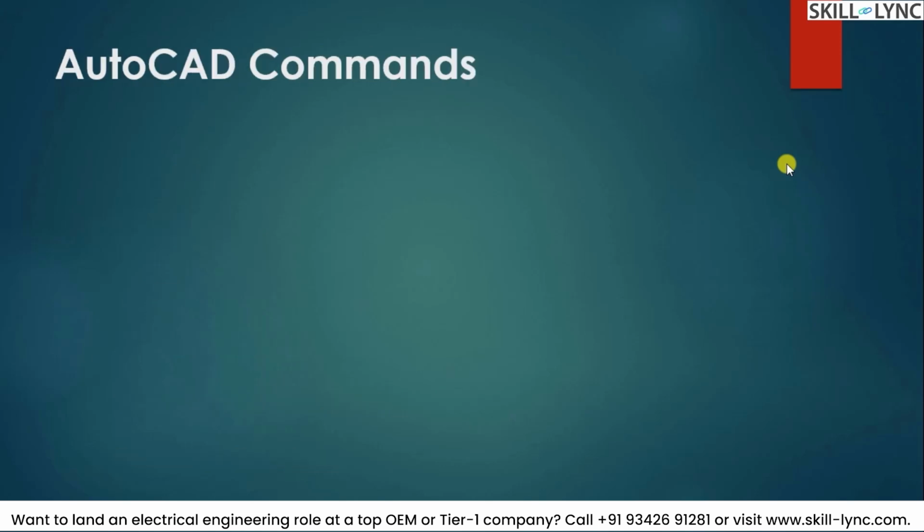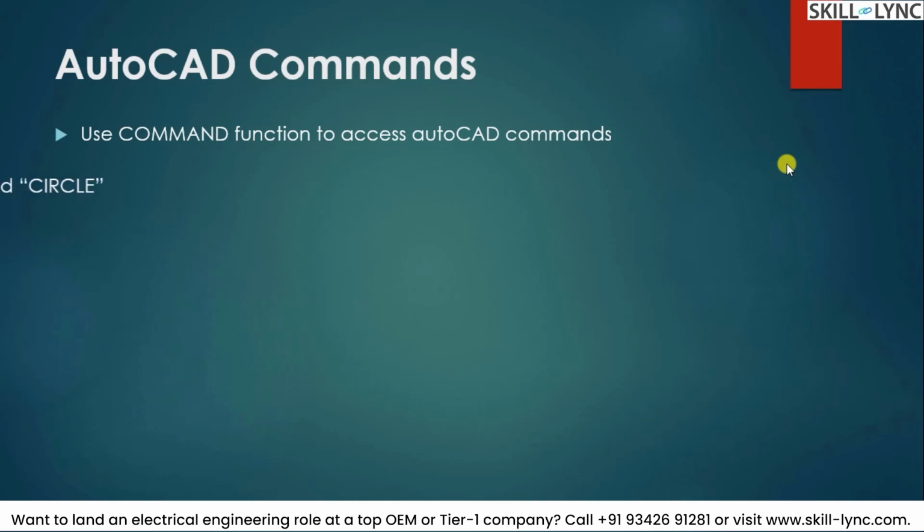So now let us go and see how we can use AutoCAD commands by itself. So the command function is used to access the AutoCAD commands that are built within the system. So for example, when you use the command function, space, double quotes, circle, it will invoke the AutoCAD command of circle. Likewise, command trim will invoke the AutoCAD command of trim function.